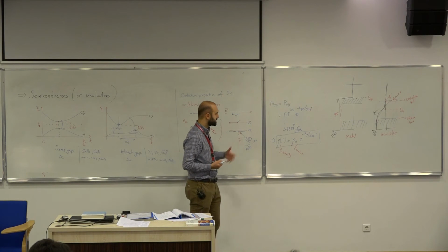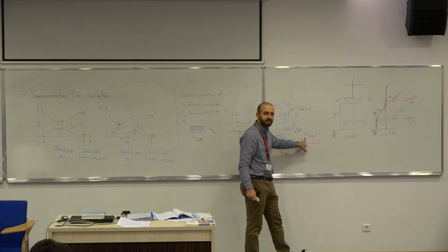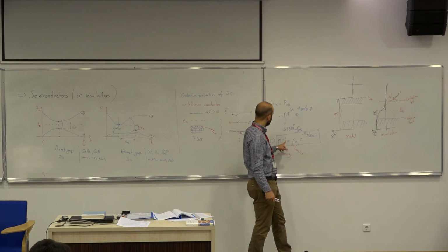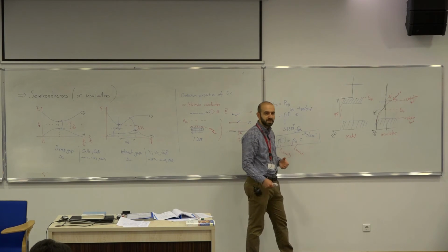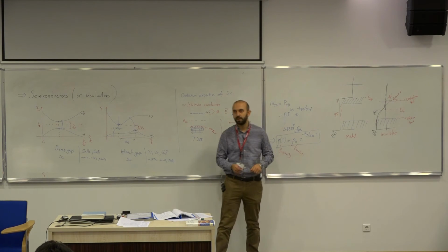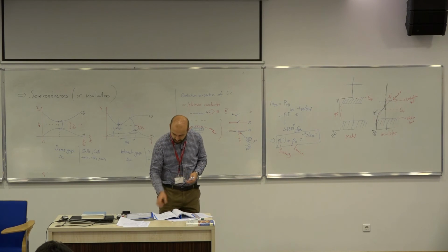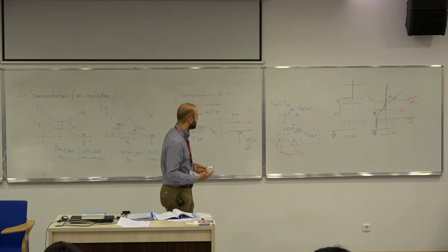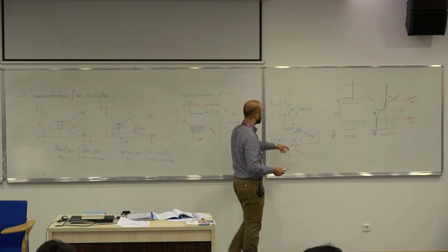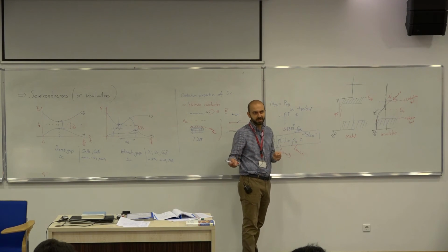And this is a significant result because, in a way, it tells you that if you measure resistivity versus temperature for a semiconductor, then you can reach the energy gap value. That's one way to do it. Of course, it's not a good way to measure the energy gap, because as you change the temperature, the energy gap also changes with temperature.